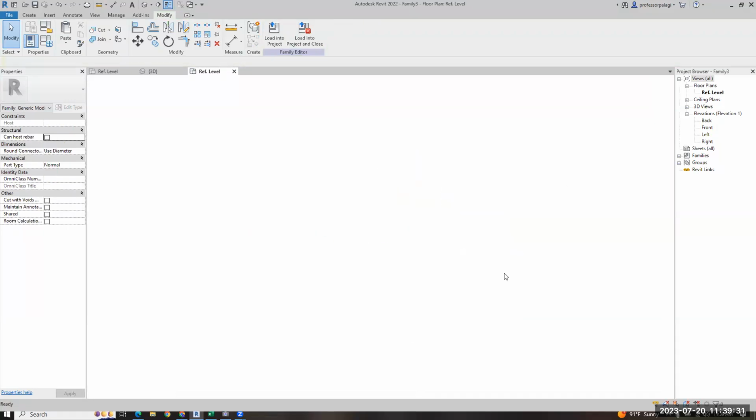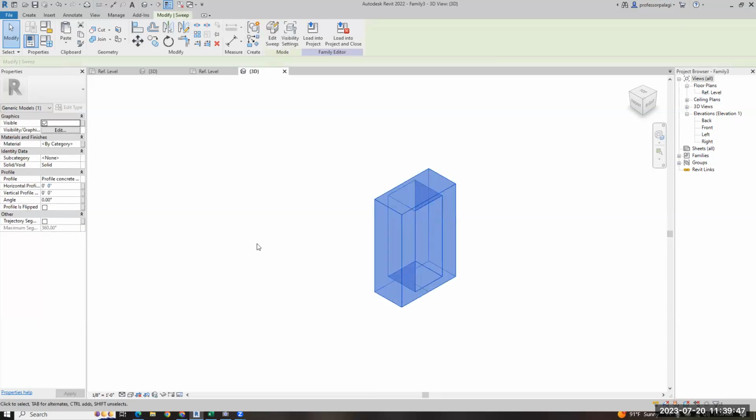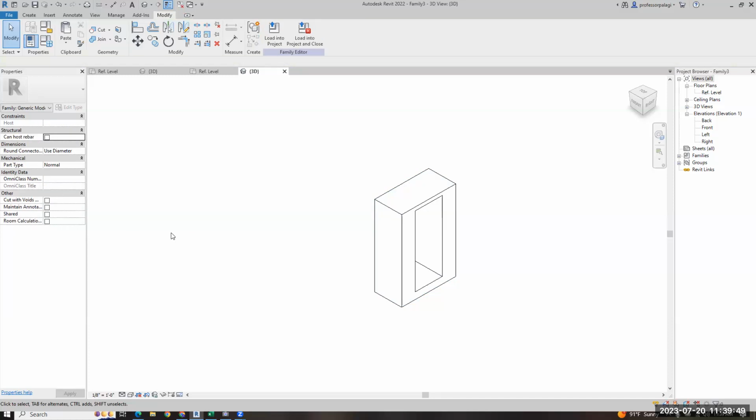Now it's this short little thing, but this is a line-based generic model. So when I bring it in, I snap 2 points, the line goes in there. Brilliant, right? So this is where, if I want to snap it around. Now, if you click always, I think you can. Think of this as a really strict version of a 2-point adaptive. The 2-point adaptive could go anywhere, and you could screw up orientation and all this stuff. If you're just making something that's going to function just like the structural beam that you want, then this works, right? So let's say file save as.